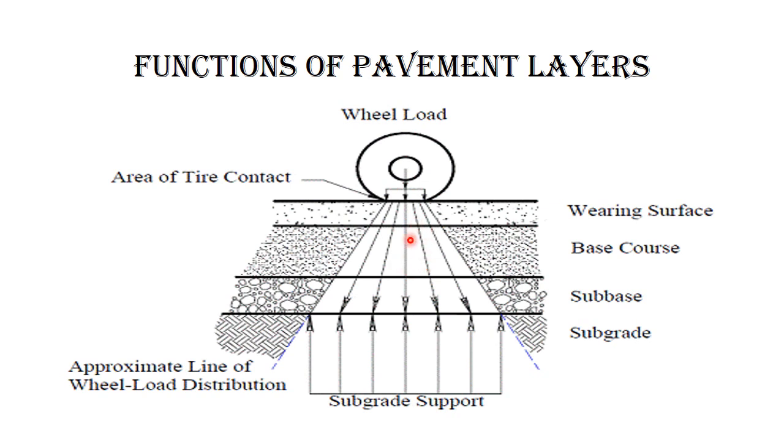The topmost layer is called the wearing course, and it is also called the surface course. It prevents the entry of surface water into the pavement layers during the rains and thus protects the base course and other pavement layers below. With a good surfacing and an effective drainage layer, it is possible to keep the soil subgrade in a relatively dry condition and retain its stability. The bituminous surface serves as a wearing course for the traffic and provides a dust-free pavement surface under dry weather.